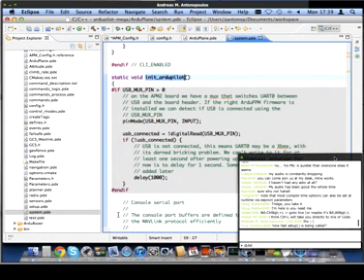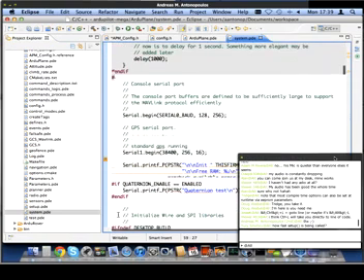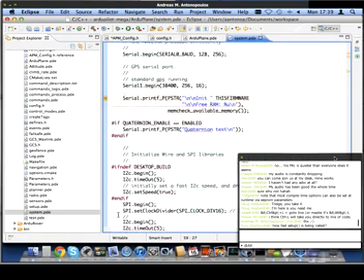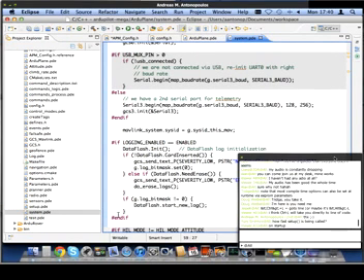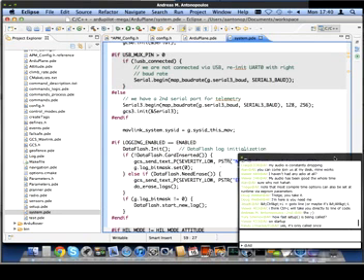So this is what sets up all of the APM or APM2 hardware. And so if you're interested in exactly how we configure the hardware, how we calibrate it, etc., then init ArduPilot is where you'd start. So you see at the beginning of that, for example, the serial.begin, that sets up the various serial ports. We have 4 serial ports, or 4 UARTs is more accurate, on the APM, and we use all 4 of them.